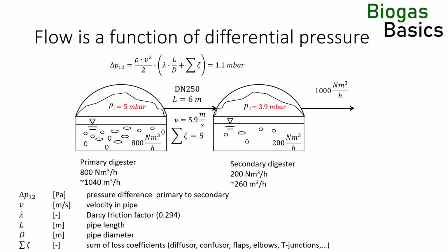When the gas dome is empty, the inner membrane lies on the belt structure. The belt structure takes some of the area force produced by the air blower of the gas dome, and the biogas space can have a lower pressure than the airspace. Other effects that can cause a difference in the flow are temperature and corresponding density and humidity changes of the biogas, sulfur precipitation, or condensate accumulation in the gas line between the two tanks.